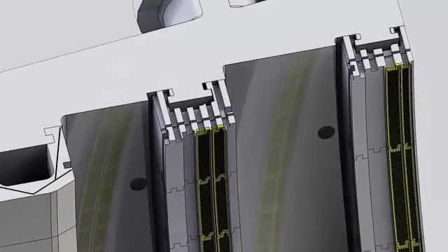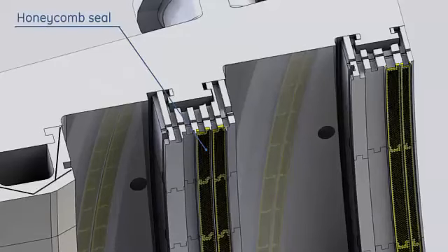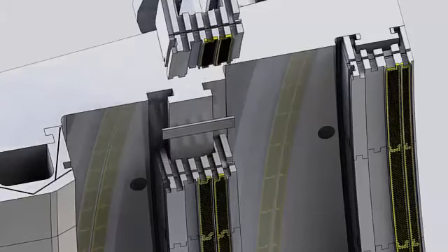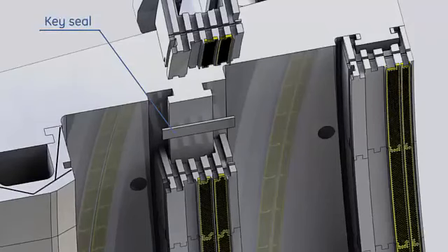The second and third stage shrouds have teeth that mate with teeth on the tip of the second and third stage buckets. This labyrinth seal minimizes tip leakage. For better tip clearance, a honeycomb seal is integrated on the second and third stage shrouds. This honeycomb is relatively soft material. The cutter teeth on the tip of the second and third stage buckets open a slot on the honeycomb seal without any material transferred, providing tighter clearances to improve the unit efficiency. Shrouds of the last two stages are sealed by interconnecting tongues and grooves and by key seals.